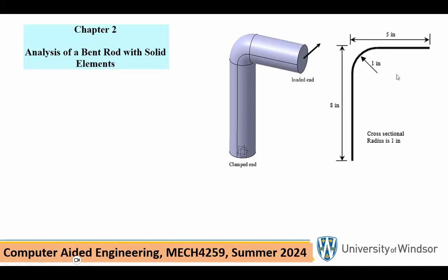You wrote the energy content of that vertical piece based on bending, and this one based on bending and torsion, and added them up and then minimized it, which was called Castigliano's theorem, or you took its derivative in a certain direction. Anyway, that's not the job of this course. Later on we're going to solve this problem as a beam problem, but not now. In another week or so.